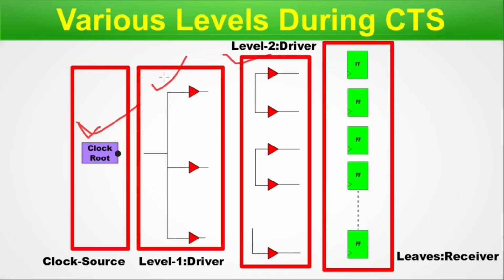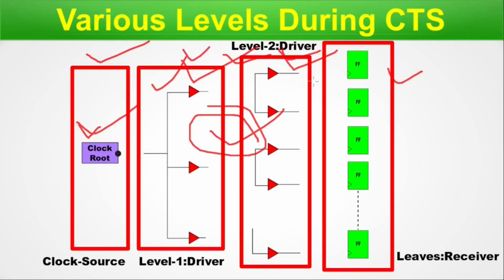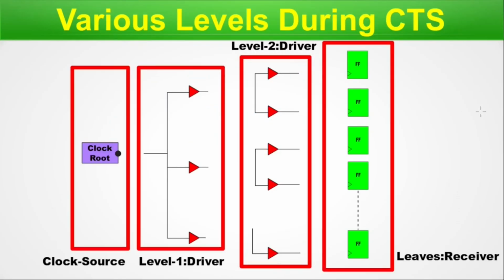The clock tree synthesis actually inserts this level, and in case there is some clock getting here, it will also be inserted. So you can see that from 1 and 2, these two levels, or more than two levels, are inserted through the CTS. The complexity of modern age, that means now we are in the sub 45 nanometer range, or rather we can say sub 10 nanometer range. The complexity and the levels are too much in the CTS.